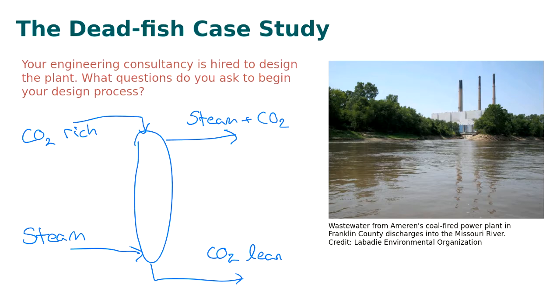And the apocryphal answer to this problem is that the consultant actually started asking around in the area and got in touch with an environmental firm that was able to report the summer was particularly hot. And in the high temperatures, the water was able to absorb less dissolved gases.